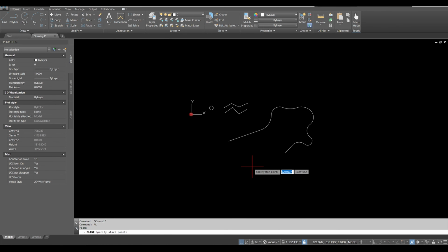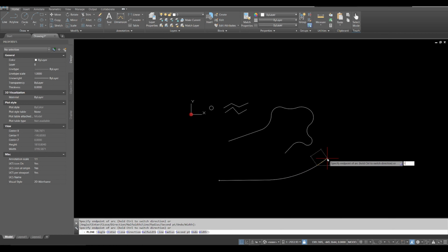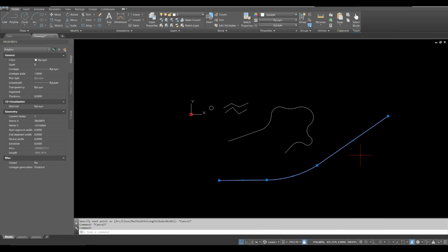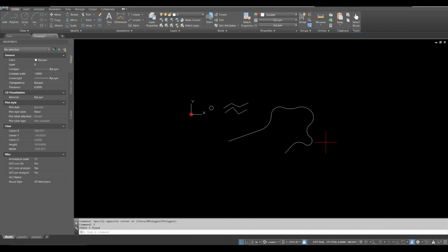So that's sort of what the arc subroutine inside our polyline command does. So once again, activate my polyline command with PL space, click, A for arc, and now I'm creating an arc, L space for line, and now I'm creating a line off of that arc. So good to practice that for sure.